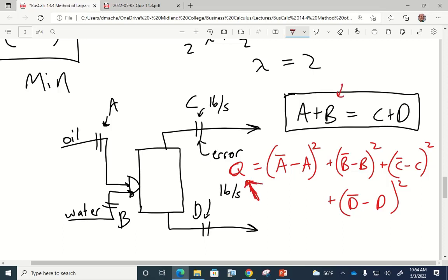But then I didn't just use one constraint equation. I was doing this for an entire oil refinery worth of constraint equations. So there was something like 6,000 constraint equations and like 10,000 flow meters. And so we were working on this huge system of equations that came from this same method of Lagrange multipliers. But the purpose was whenever you do this, you actually get values for your measured flow rates that make sense, like in the physical world where you can't delete mass or introduce new mass.